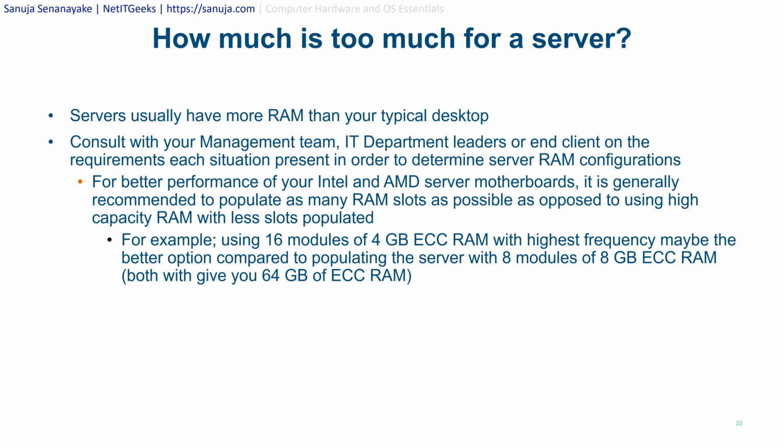For better performance of your Intel and AMD server motherboards, it is generally recommended to populate as many RAM slots as possible, as opposed to using high capacity RAM with fewer slots populated. This is just a rule of thumb that I've been told by my instructors and my professors at the university, but this rule of thumb may change as the technologies are changing. So keep that in mind. Take that with a grain of salt, but for now, it is generally recommended to populate as many RAM slots as possible.